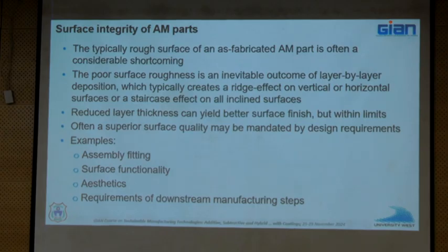But let's talk a little bit about surface integrity of AM built parts. We didn't talk so much, but a typically built AM surface is rough. The context may vary. How rough, that may change, but it's always rough. EBM is very rough, SLM is rough, DED locally is not rough, but on a macro scale it is undulating a little bit.